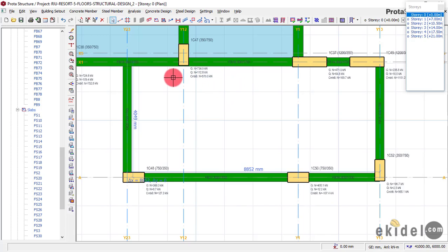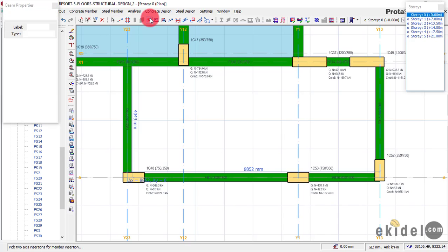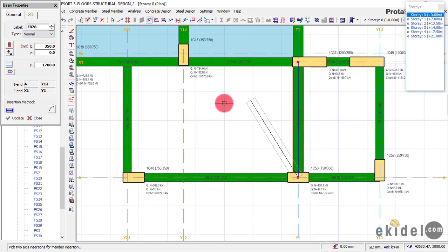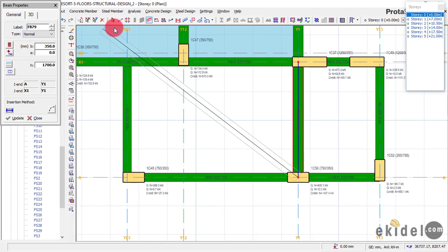So in this case now, this panel is already too big, more than the required area of 30. So right now, to break this panel, I have to introduce a beam here. I'll take that beam and then come here and click on this and then click on this here. So right now, if I check these two panels, you can see that they are less than 30 meters square area. So right now, I'll come here and then say close, okay?